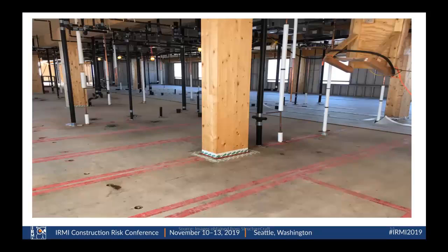This is showing you what it looks like on the surface before we place the gypcrete. We've got actually on the perimeter of this, the initial design showed L angles that would house the gypcrete. Instead of that, we actually oversized the bottom track of the walls so that it would capture the gypcrete and keep it in.